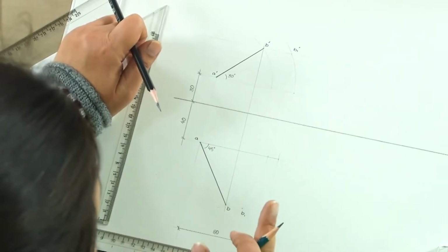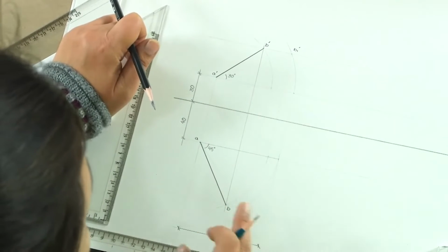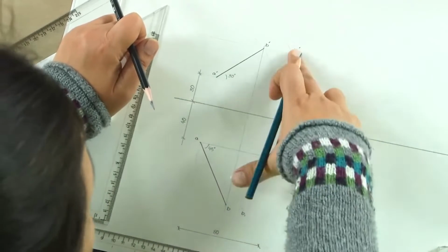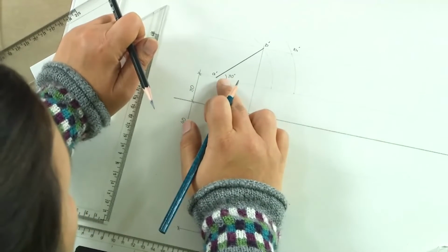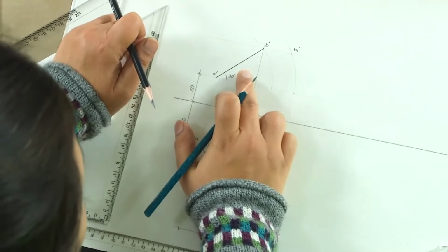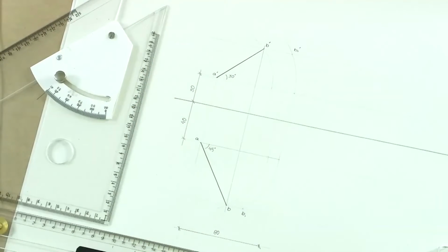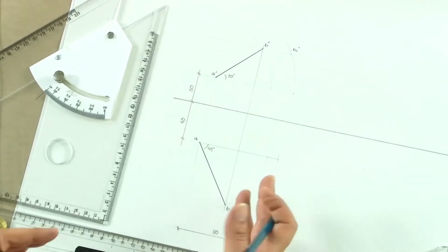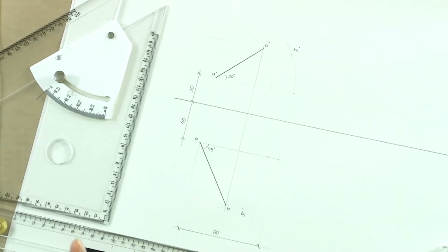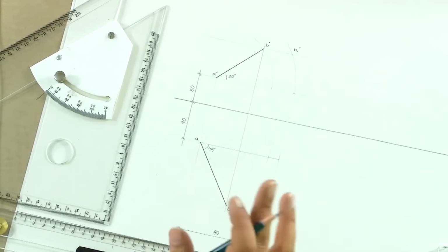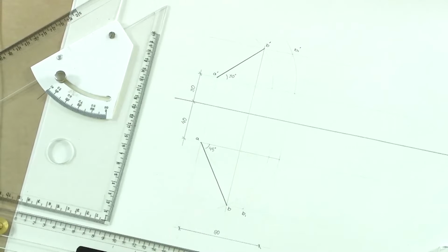And then we will draw the true length of the line. If the true length of the line is given to us, we will draw the true length of the line in both the places, and then we will calculate the true angle of the line that it makes with VP and HP. So, that is what we can do in order to calculate in reverse the angles that the lines make. Now, where would this be necessary?